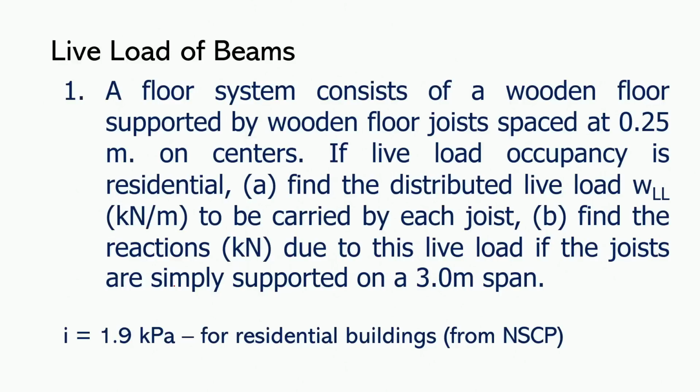If live load occupancy is residential, find the distributed live load WLL to be carried by each joist. And also find the reactions due to this live load if the joists are simply supported on a 3 m span. Now, given na dito na for residential buildings, kasi again, yung load occupancy is residential, I is equivalent to 1.9 kPa. That's from NSCP.